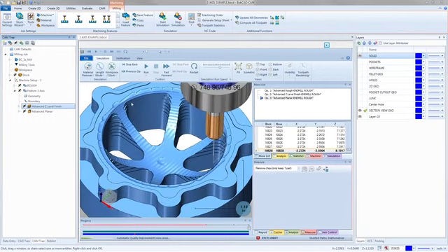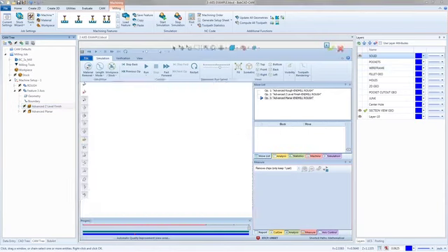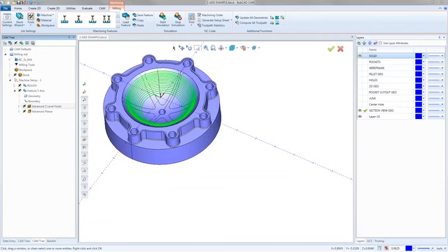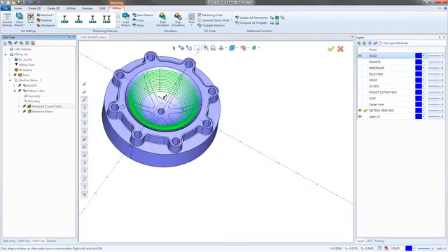You may want to rough it out and leave that surface on there when you rough it. Who knows, you might want to put the pockets in. Well, you can't put the pockets in from the bottom side on this part because the walls are tapered. So no matter what, we have to go in and do a bit more machining on those walls. For that, I'd probably just do another Z level with a smaller tool. I'd turn off that surface and let it run. But other than that, it looks pretty decent.